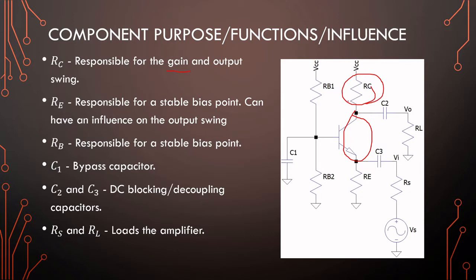Now the common base typically has a very large voltage gain, but it's not a nice voltage amplifier because it has a very small input impedance, looking backwards at R pi and that becoming small RE, which is a very small impedance, but makes matching with other circuits for low impedances quite easy.